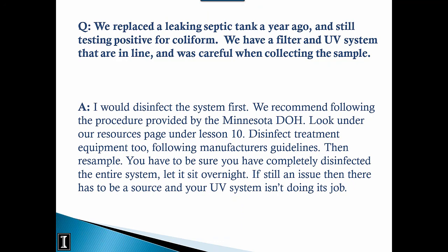It's got tables on how to mix the chlorine. It just has a lot of good safety practices. And if you're not comfortable disinfecting your own well, then you should call a contractor and have them do it for you. But if you look under lesson 10, you can see that information. Basically, your equipment, your filter and your UV system should have information on how to disinfect those as well. And if you don't have that information or you've lost it, the Water Quality Association probably can get you information on those practices, or the manufacturer.